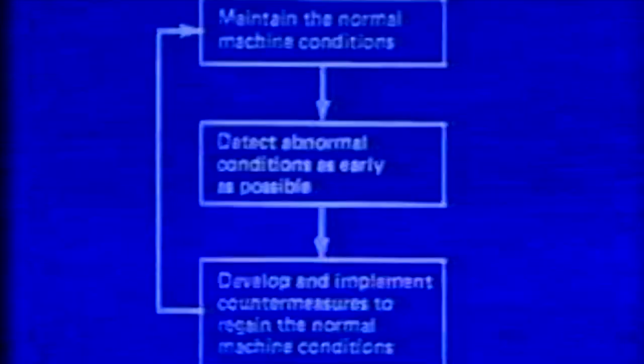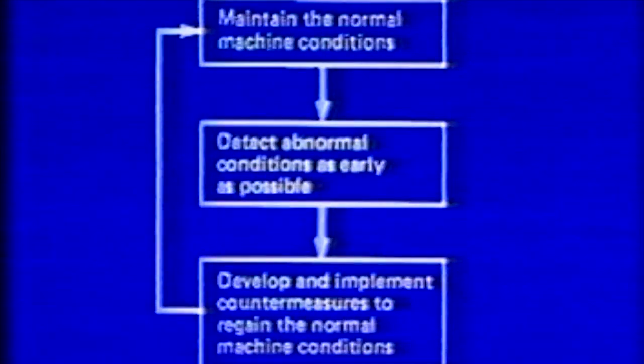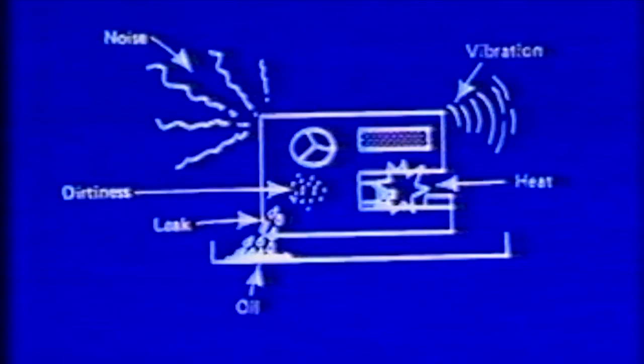Just as inspecting parts after the defects are produced can never totally eliminate defects, we cannot establish trouble-free operations without addressing the issue at the source. This shows an approach to preventing them. One of the key points here is the realization that people themselves are the cause of the problem. Typically speaking, machines do not create problems by themselves. Rather, people let machines break down, for example, by forgetting to oil, or retighten bolts, or by leaving the machine dirty, or perhaps by not following the proper instructions.